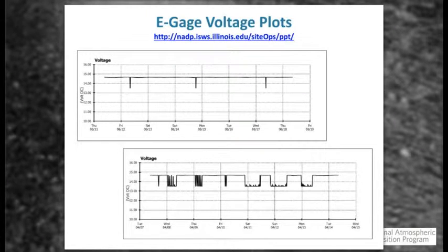In the bottom one, especially with long precipitation events, the line power is dipping and it's not coming up again. The higher mode is probably when the sun's out. The low mode is especially overnight, if you look at Saturday and Sunday, where we're not getting enough solar generation capacity, so the voltage is dipping down, and it might indicate some sort of battery capacity issue.